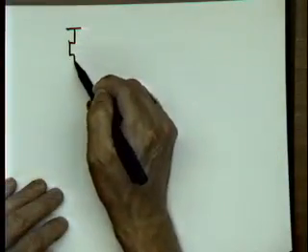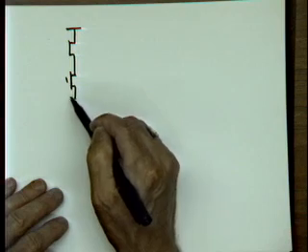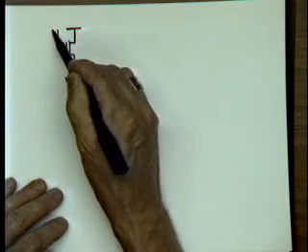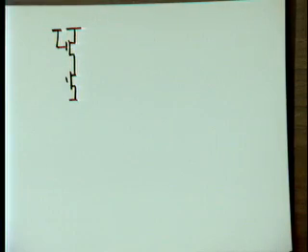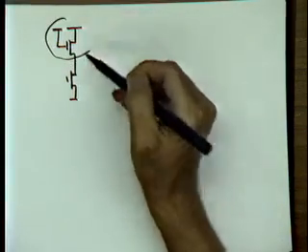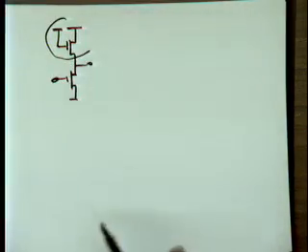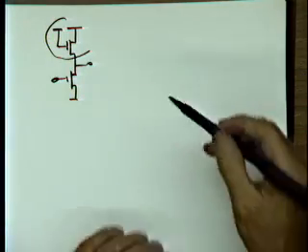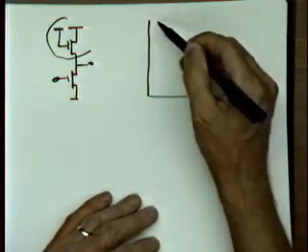Question? I think we've seen 3 different types of inverters, the CMOS and then 2 different NMOS inverters. Is the CMOS the only one that's regenerative? That's a good question. We showed you some other inverters during homework, like the one we call the saturated load inverter. That's one example, where you use an NMOS as a load, and this is the output, this is the input. If you look at the voltage transfer characteristic of this one, it's not as good.